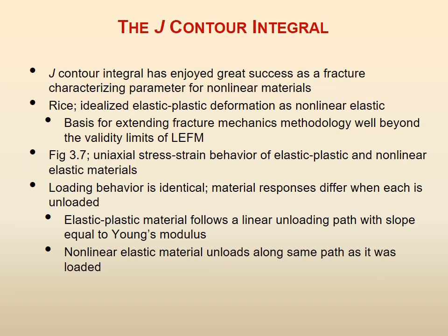So that was CTOD. Remember, CTOD and J integral are like K1 and G. When linear elastic fracture mechanics was there, the whole of fracture mechanics was described by two major factors with which you could find the fracture toughness of the material, either K1C or GC.